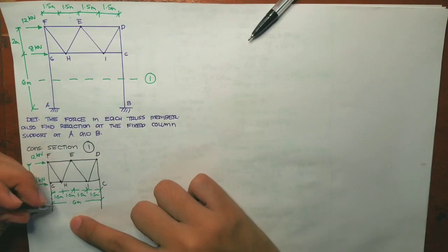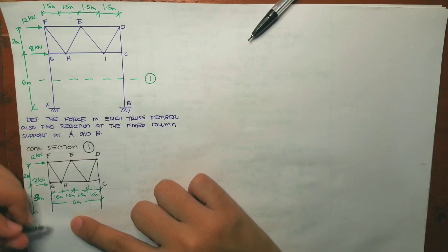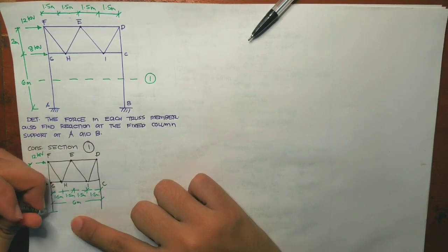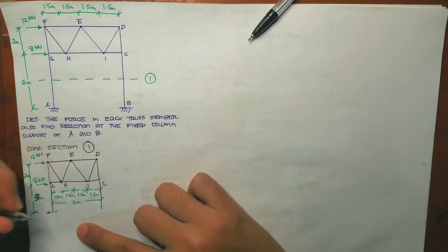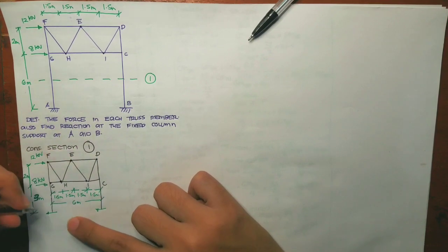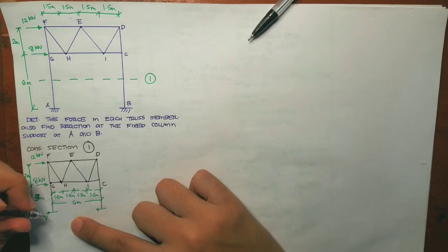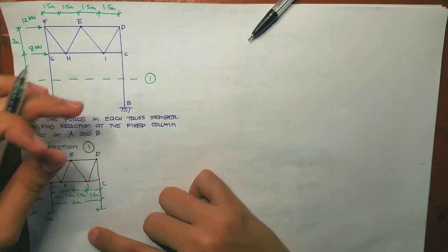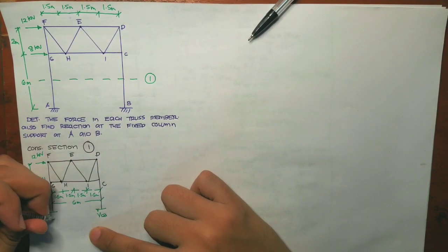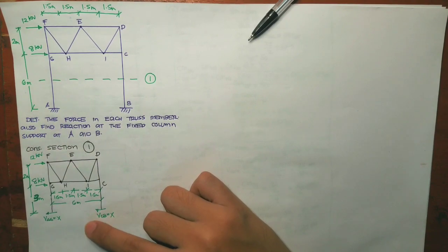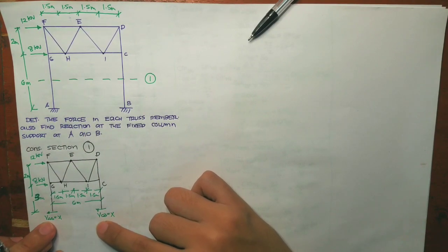Okay, so let's name the internal forces in this column. Again, this is an external column, so no need to consider the internal column or the 2V from our previous example. This is your shearing force, denoted by V. Let's say this is the shearing force for the column AG, and this one is the shearing force for CB, which we say are both equal to X. And with that, the value of VAG and VCB is just the same.